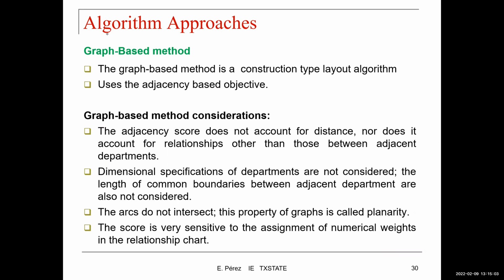The graph-based method looks similar to the SLP procedure that we just discussed, but now we're going to have a quantifiable function that is going to direct us on how to proceed in terms of moving departments in the facility. So the graph-based method is a construction type algorithm. This is used if you don't have an existing layout. Construction is basically under the assumption that you're building this facility from scratch. And this uses the adjacency-based objective.